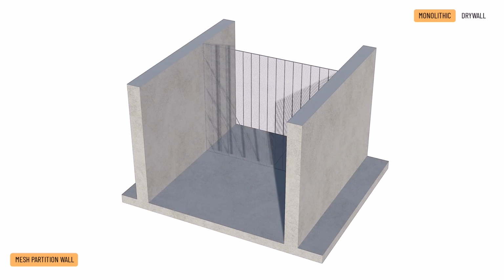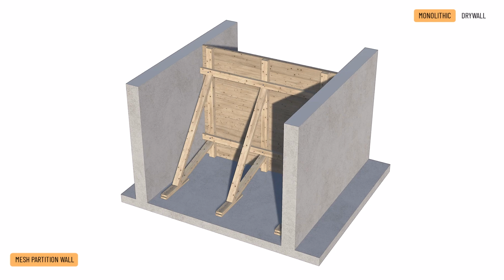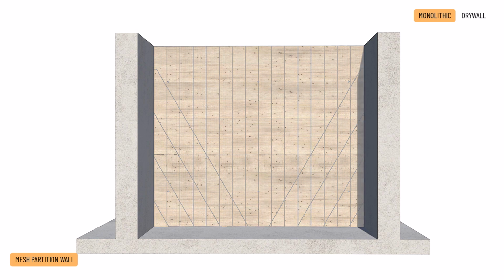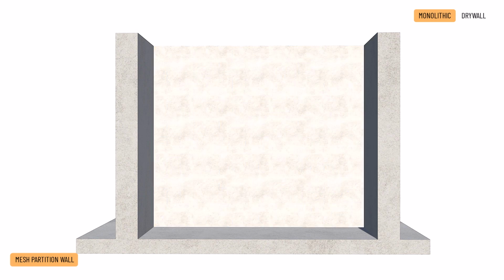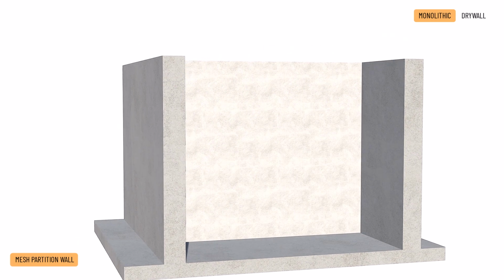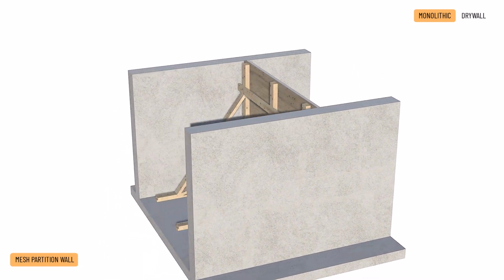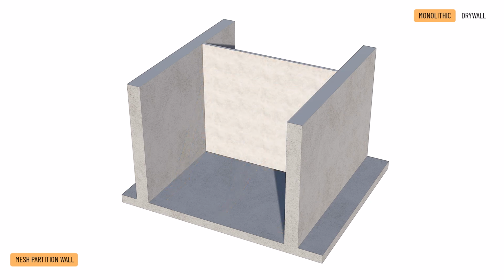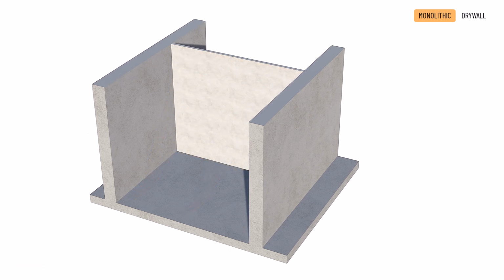using inclined rebars. Behind the supporting layer, a single-sided formwork is built with a 5-10 centimeter thick layer of gypsum or cement plaster applied to it by hand or machine. Gypsum plaster is a mixture of gypsum, lime, sand and adhesive, while cement plaster is a mixture of cement, sand and slag. After smoothing the surface, the formwork is removed and you have your partition wall.